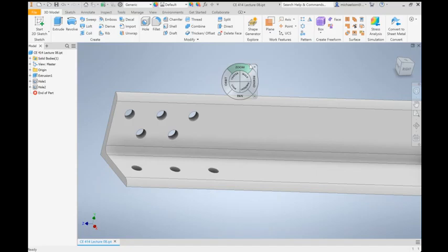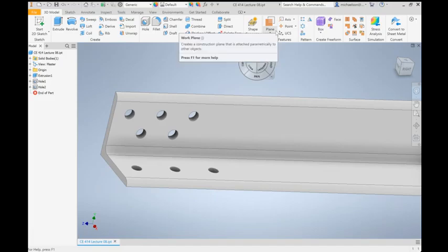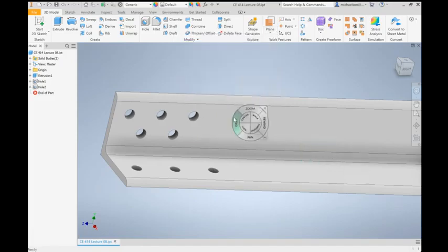So it wasn't me looking at it and just saying, well, it's going to be this and this. You have to look at the connection and identify all of the possible paths that keep those bolts intact. Now, if I had just drawn a single path that goes like that, yeah, sure, this bolt is on the lead line, but imagine I fail along that path and yank the member. Not only am I separating the member, but I have to shear these 2 bolts in front, and that would violate the rules that we've established.